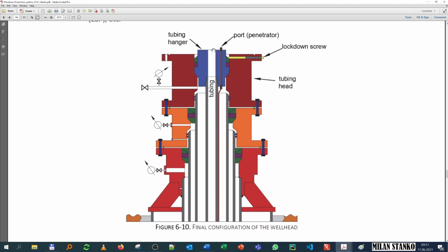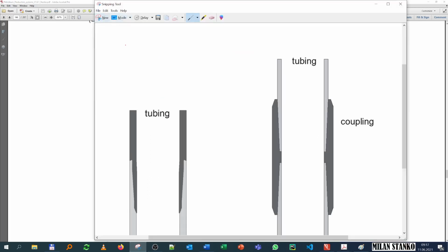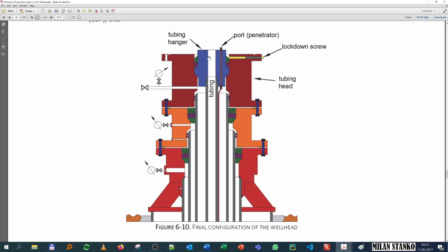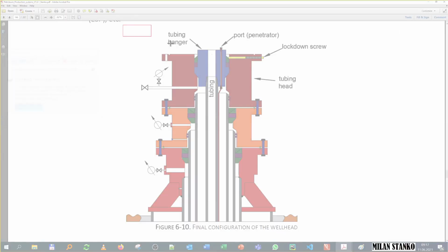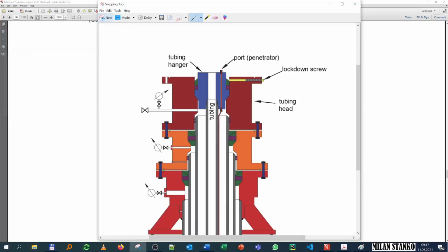The number of ports and the space you have is limited in the tubing hanger, so that's something we should take into account. Maybe we cannot go that high. We would like to have a very big tubing, but we cannot, because the well has a lot of things inside that we have to have lines for. And here you see the shoulder is a bit bigger, but it's not as big as I put it on my sketch.